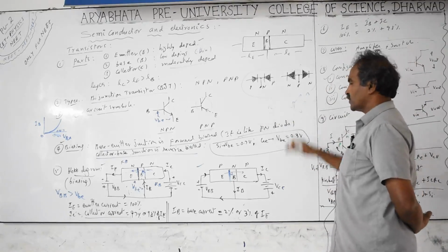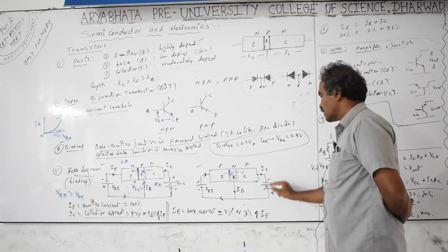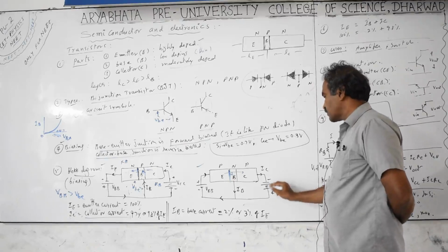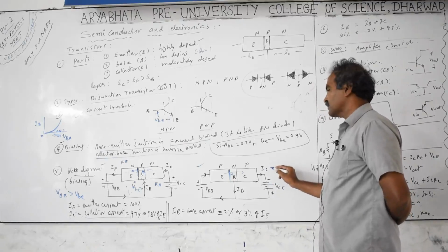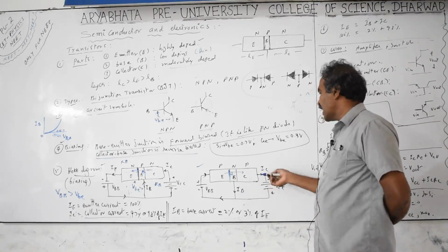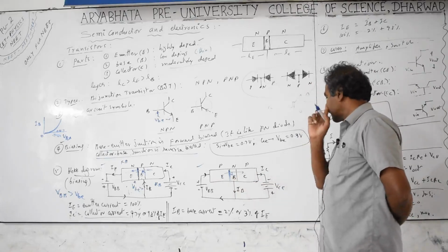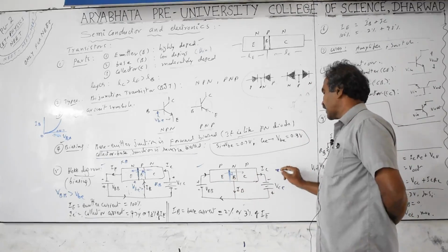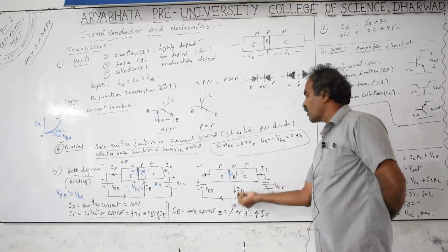We don't increase the voltage just like that, we take the help of the bias voltage. With more bias voltage we get more current. So we always get IC very large compared to IB. This IB is called the input we are giving, and the output is taken from the collector, not the emitter. Taking the emitter is a special case, but mostly we take the output from the collector, because the collector current is more, so the output will be more for small base currents.